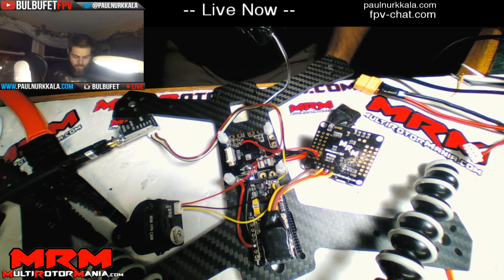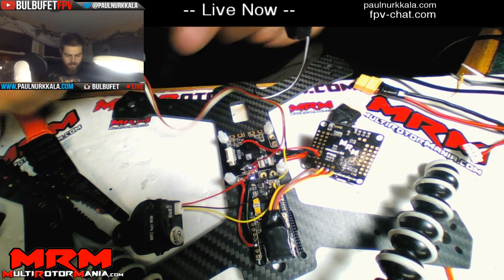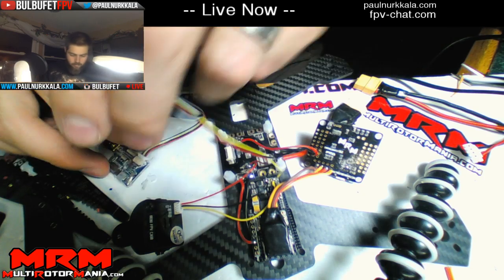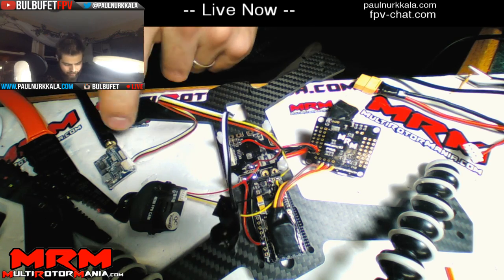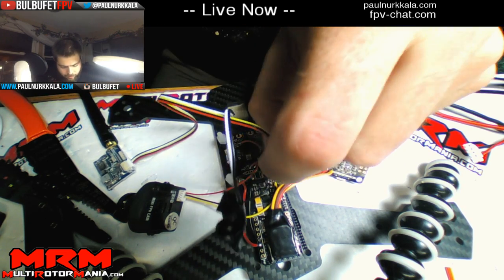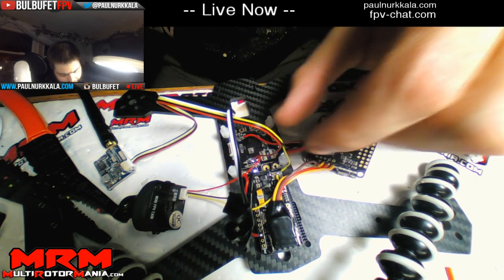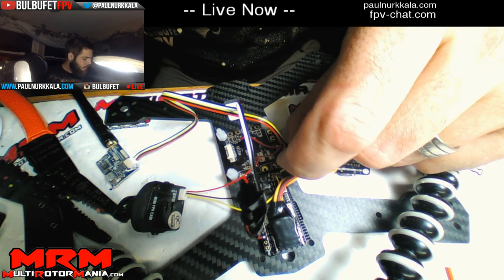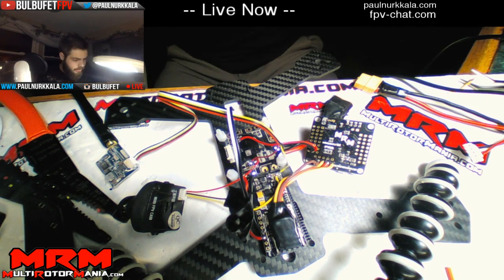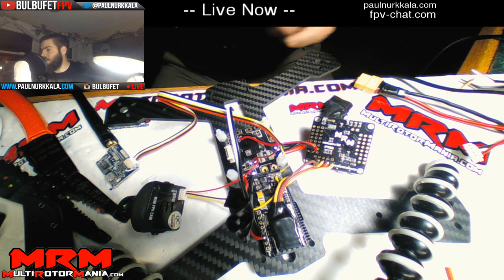Okay. Ugh, I hate powering stuff up. All right, so we have VTX. We've got power to power, ground to ground, and video to video out. Let me make sure that's video out. I'm 99% sure it is, but it's always worth double checking.